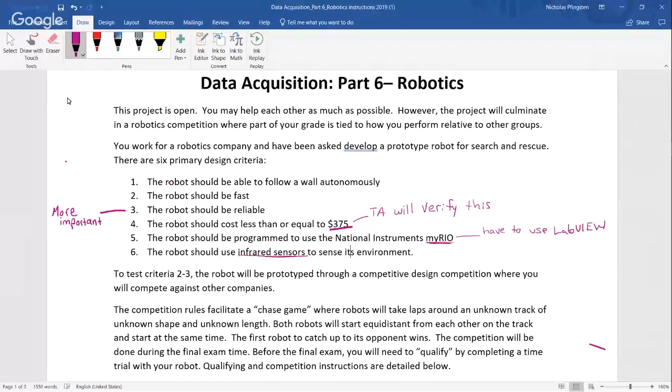We have a very few number of long-range IR sensors. So those guys that have to know, make note of the fact that the long-range IR, its max distance detected is about 1.5 meters. Whereas the short-range IR, its max distance detected is, according to the data sheet, 80 centimeters. All right. So you get a lot more distance with the long range.